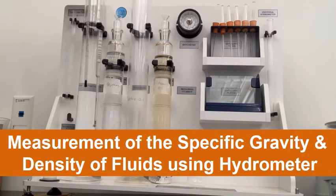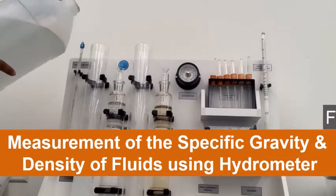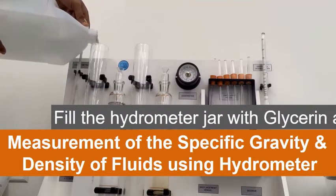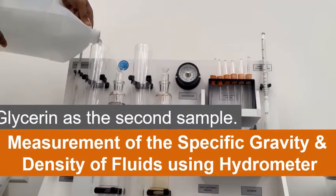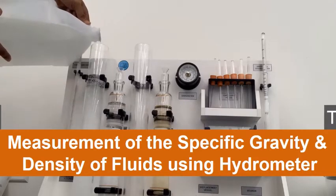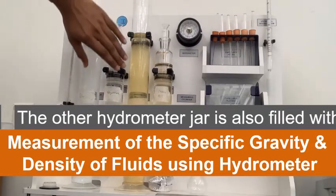Very slight difference. Now we remove the water and we will replace it with glycerin. So we'll pour the glycerin up to the top, to a level at which the universal hydrometer can float. Same thing we did with the castor oil for the second hydrometer jar.